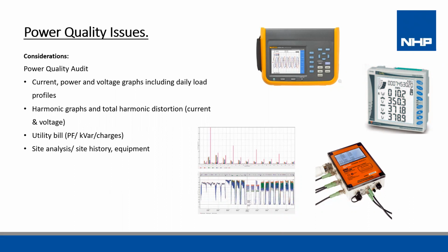It is also good practice to check the power factor through on-site equipment or metering. It is best to check during peak load, so as to ignore or remove any unnecessary data, as during peak load it will give you the most accurate indication of what is actually happening on site, and as a result, it will show you the correct reflection of the power factor and any harmonics associated with that.